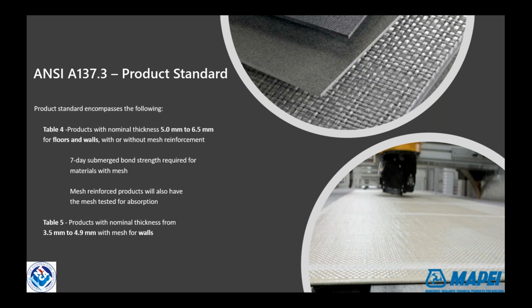The product standard includes measuring for nominal thickness from 5 millimeter to 6.5 for floors and walls, with or without mesh reinforcement, like you see here on the back of this one, or being applied there. 7-day submerged test for strength with mesh, and then the mesh itself is also checked for absorption as the tile is. Table 5 includes products for walls, and that's 3.5 to 4.9 millimeter. So thinner materials for walls, thicker materials for floors. Makes sense.